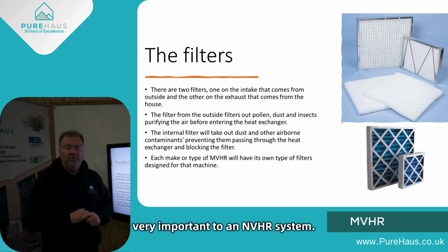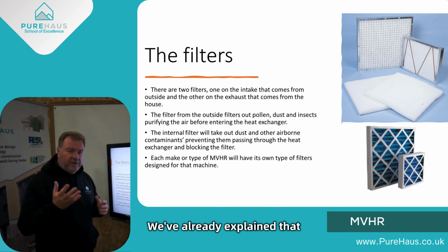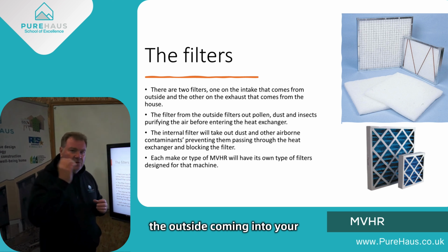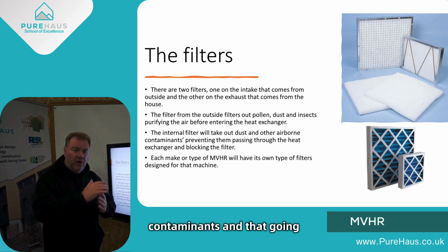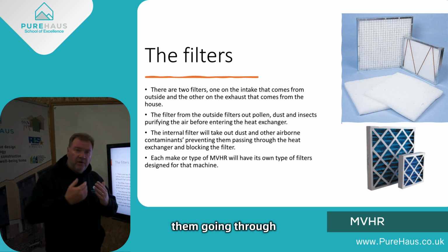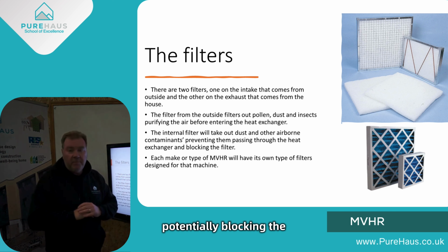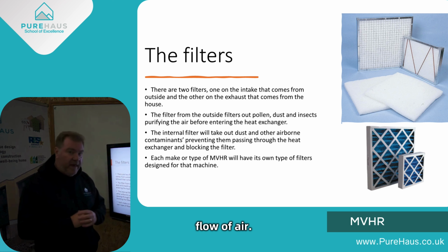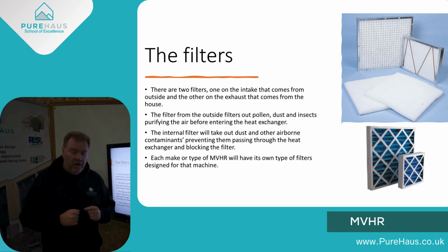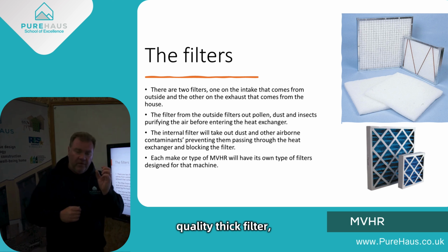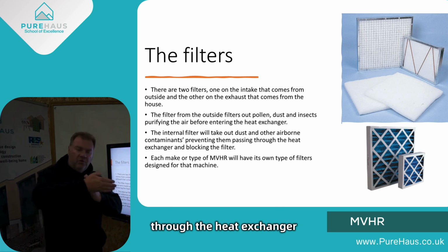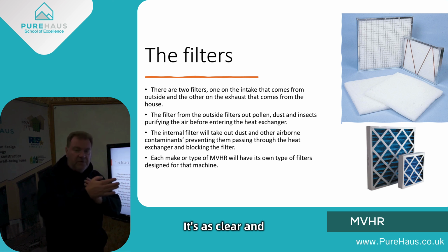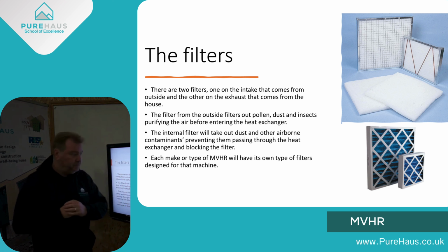Filters are very, very important to an MVHR system. We've already explained that when you get air from the outside coming into your machine, we don't want contaminants going into the build. We also don't want them going through the heat exchanger, potentially blocking the flow of air. So we have some really good filters. Usually you have a really good quality thick filter which takes out all pollen and all really nasty contaminants from the outside. So when the air goes through the heat exchanger and into the build, it's as clean as we can get it.